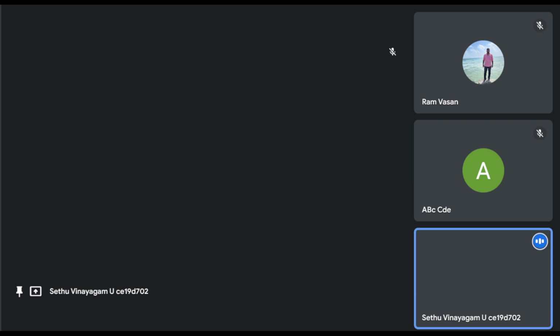Or this is also regarding the coordinated signal, right? So when you go from one intersection to the other intersection, if you are able to cross through without stopping, then you will have a coordinated system. That will give you a coordinated signal, and a better platoon progression, right? So that is related to warrant 6. And warrant 7 is about accidents, crash experience.